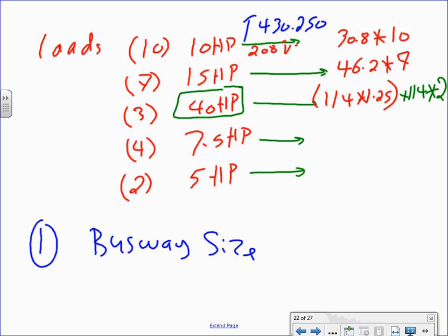You take one motor, which is the largest, add 25% of it, and the other two just add. I know this is confusing you. There are 3 of these motors, right? One of them will be considered the largest, right? So you take the largest, multiply it by 1.25, increase it 25%, then add the other 2 to it.